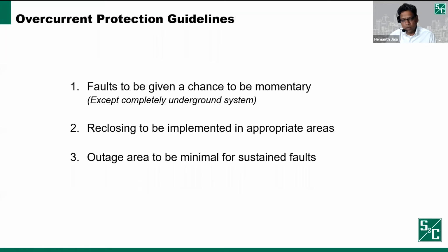Second one is you want to use reclosing in appropriate areas. Reclosing is basically going through a sequence of operations, using reclosers. What we mean by appropriate areas is you want to use reclosing in residential areas and not in an industrial setting where you have large machines going, you don't want to reclose into something like that. For residential areas, you can do that, and predominantly utilities would be favorable in doing that.